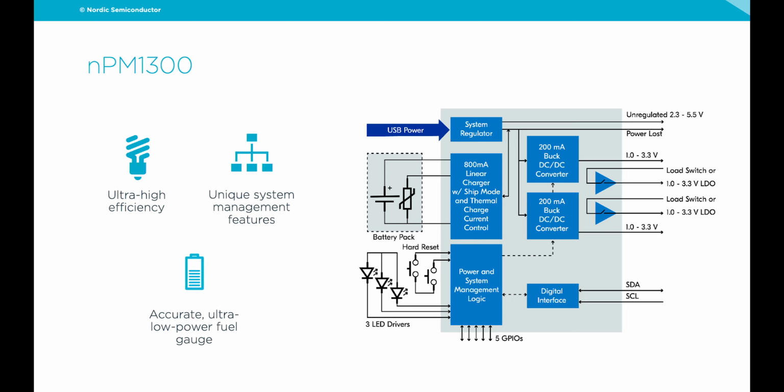If we look at the diagram here, you see there are some useful features integrated. For example, you have a hard reset. You have some normal features that you would expect in a PMIC, for example, the load switches and LDOs. You also have this digital interface that allows you to use some of the pins on the PMIC as GPIOs for your host processor. So there's a good reason the headline here is the most intelligent PMIC on the market.